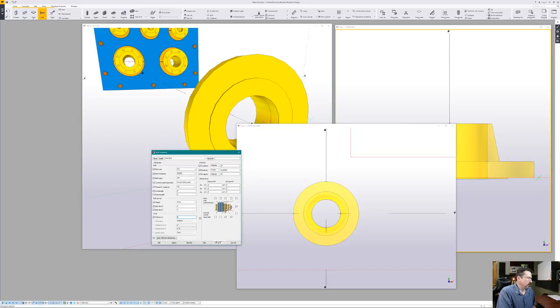Next thing I'm going to do is, we're not showing the bolt. Over here there are 3 check marks, which are the default. The one on the end is for the bolt itself, and then going around, we have the nut and then the washer. We're not going to show the bolt shaft. If you uncheck that one, it automatically unchecks everything else, because if you're not showing the bolt, you obviously don't need to show anything else. So with that, we will apply.